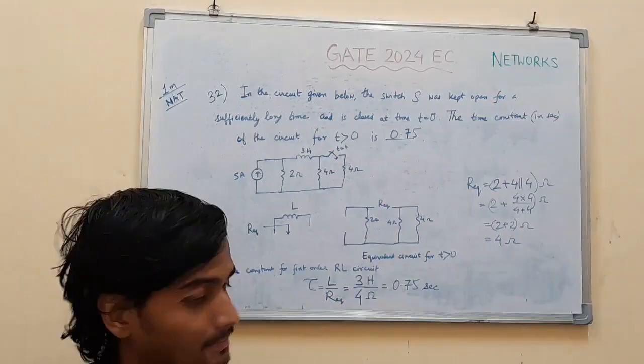Now, what can you write? You can have a KVL in the right loop. KVL in the right loop is V2 equal to 4 into (I1 plus I2). Minus, because we have taken the drop as positive on the edges, so rise will be negative, so minus 8 V1.